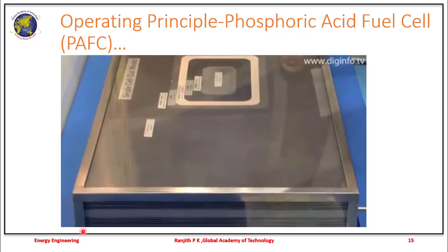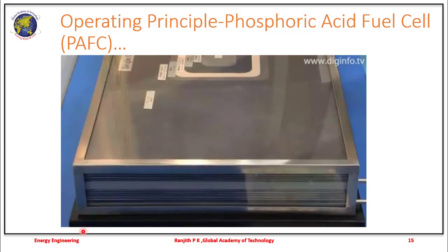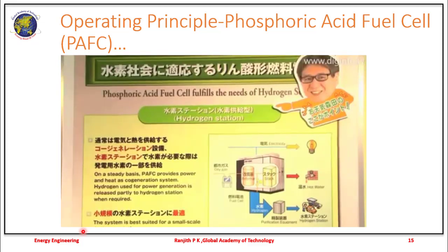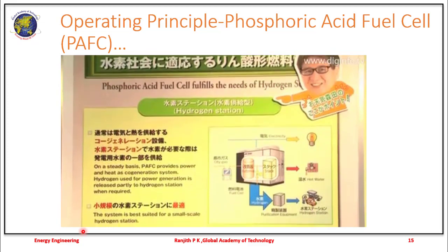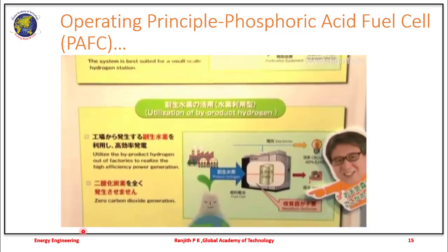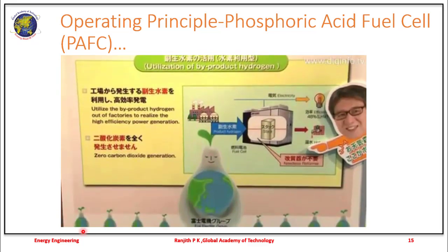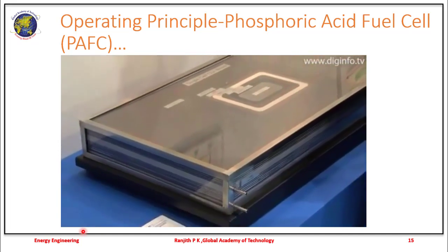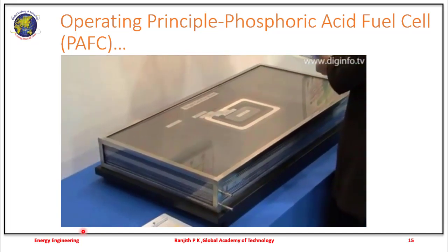There are several types of fuel cells that use different methods for generation. For this phosphoric acid fuel cell, Fuji Electric Systems developed high-precision control technology that ensures steady reaction in the three phases of solid, liquid, and gas. Namely, the solid electrode, the liquid phosphoric acid electrolyte that creates the ion path, and the hydrogen and oxygen gases. With this technology, the company has already achieved an operational lifespan of over 40,000 hours with the commercial fuel cell.